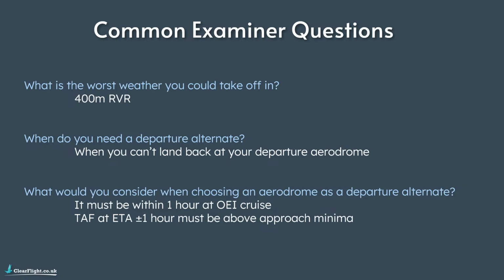As we've just said, it must be within 1 hour at your one engine operative cruise speed, and the TAF at the ETA plus or minus 1 hour must indicate the weather will be above your approach minima at that airport.